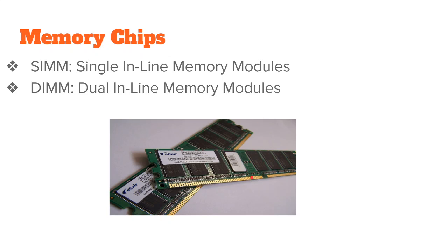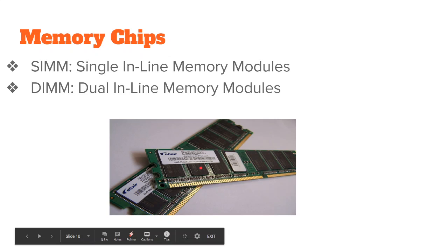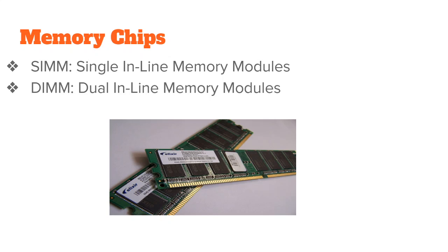These chips are packed into small plastic or ceramic dual inline packages, that is DIPs, which are assembled into a memory module. A typical motherboard has 4 SIMM sockets capable of taking either single-sided or double-sided SIMMs. The memory module sizes include 4, 8, 16, 32 or even 64 MB. When it is 32 MB used with the processors, they have to be installed in pairs, with each pair of modules making up a memory bank.